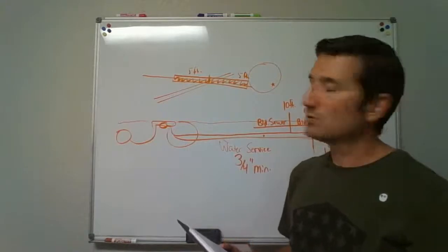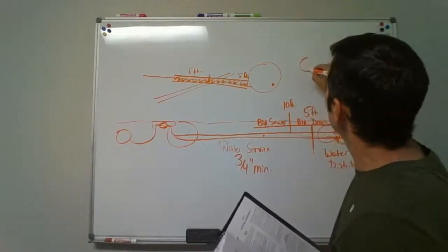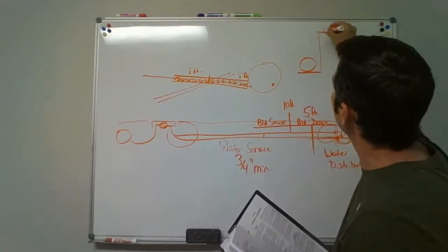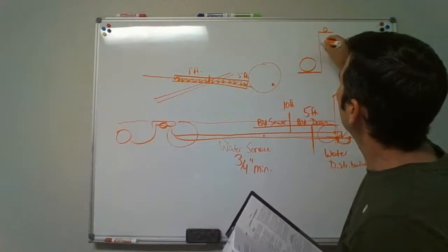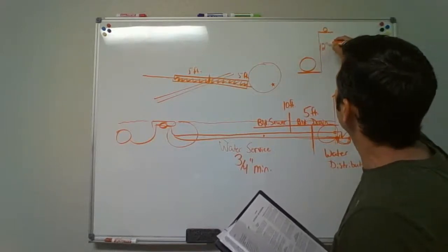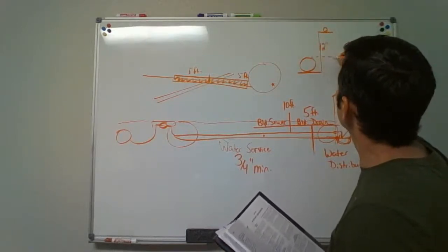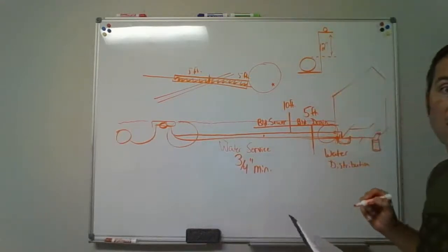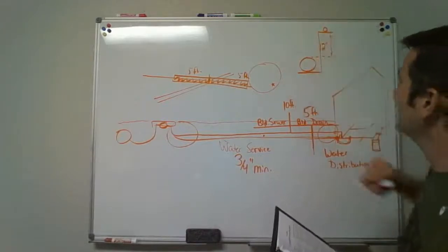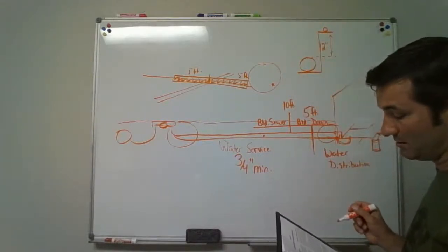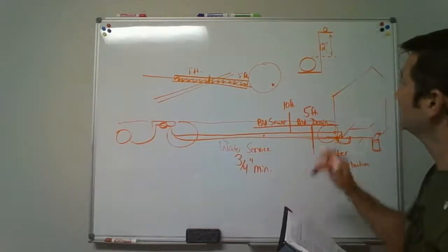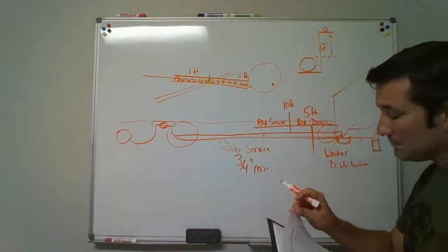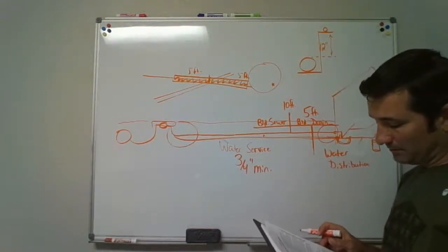There's another thing that you can do: you could have your sewer line down here in the bottom of the ditch, ledge your ditch off, and have the water line sitting up here, as long as you've got 12 inches of separation between this one and that one. Okay, so if you can do that and have 12 inches of separation there, then you're fine. And you can notice that I measured it from the top of the pipe, the highest part of the pipe. All right.